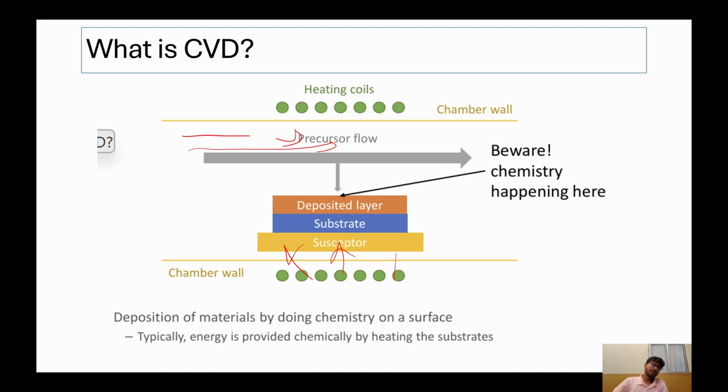Over the substrate there is a susceptor, which is of good quality and can sustain higher temperatures. It is quartz or something, which should not contaminate the chamber itself. If there are soda lime glasses, there can be sodium or potassium contamination to the wafers, which is not desired.